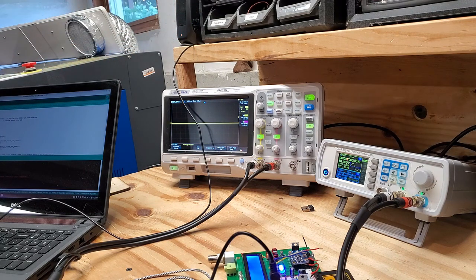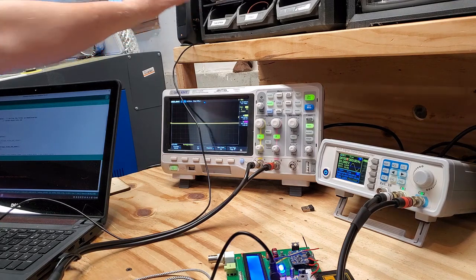That is obviously quite hideous, but that's the indicator that there's too much processing, and you need to either reduce the sample rate, 44 kilohertz down to say 16 kilohertz, or reduce the number of taps. Let me just turn that right down, it's quite annoying.